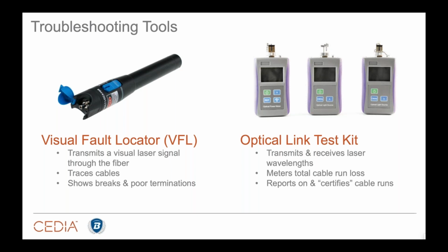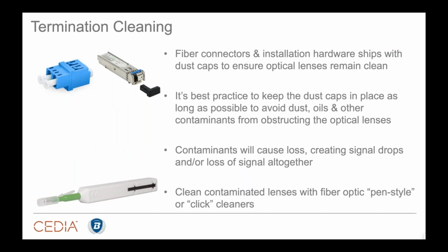But I will tell you that a significant portion of the time, folks find out, yep, the connectors are put on there properly, everything looks pretty good, but I'm still calculating out more loss than I should have. And this is why clean connectors are so incredibly important. So let's take a step back.